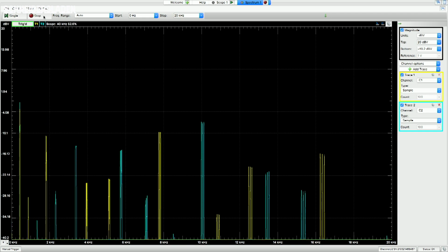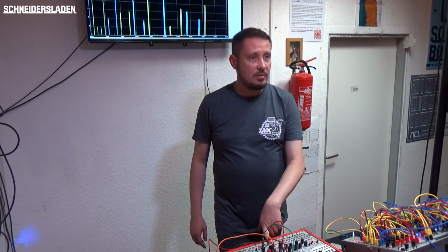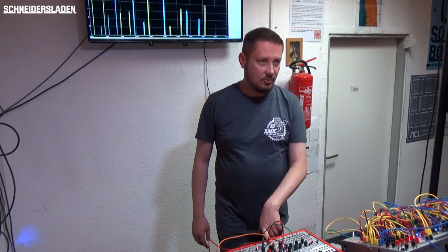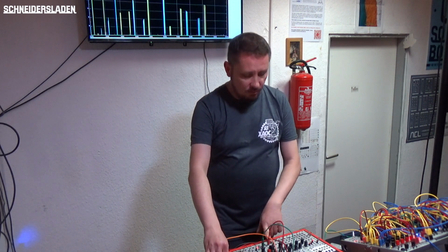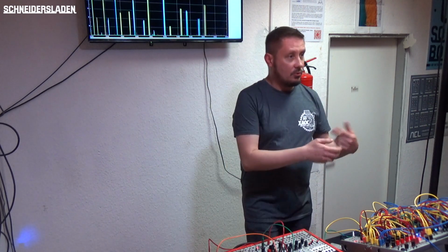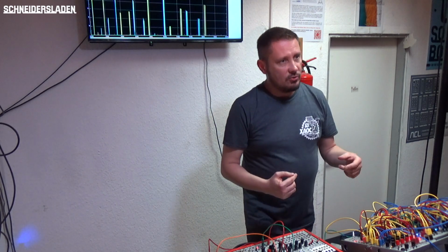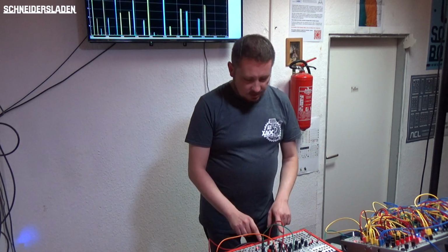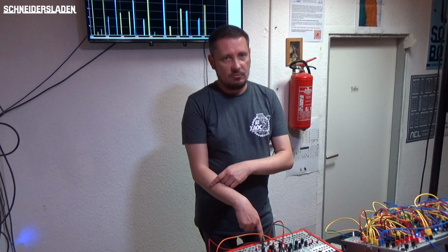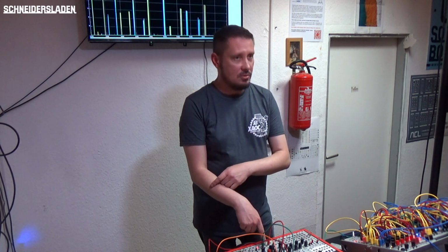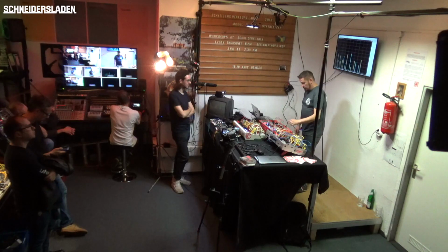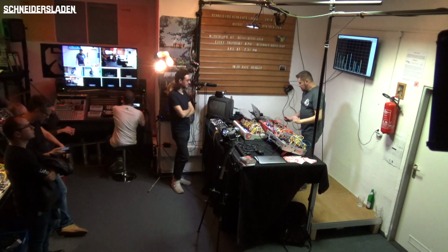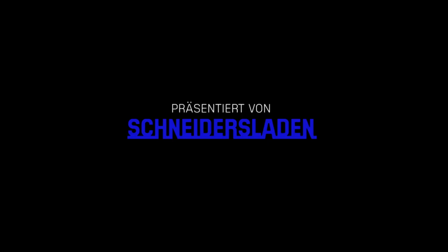We have a linear input for linear frequency modulation, through-zero frequency modulation, and since modulating very complex waveforms with through-zero deep modulation produces very harsh sounds, it's best to use the fundamental separate output, which is just a sinusoid. This also will be modulated by this linear FM input. So that's it.